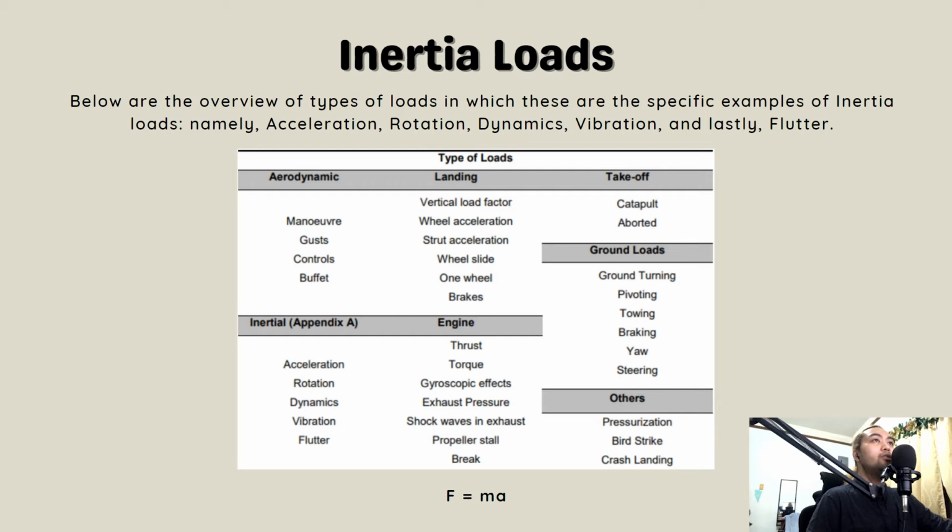Now, inertial loads are the maximum load on any given part of an aircraft structure that occurs when the aircraft is in acceleration. The loads produced are the landing impact, maneuvering, gust, boost, and staging operations, launches, and dockings, which are always greater than that of the loads occurring when all forces upon the aircraft are in equilibrium. It is important to determine inertial loads acting on the aircraft before going on to any design regarding structural components.